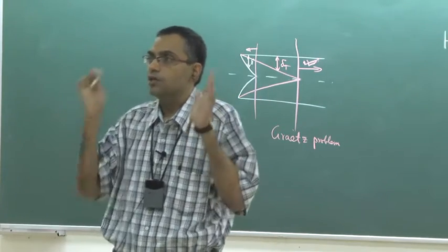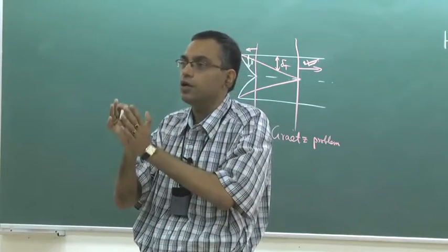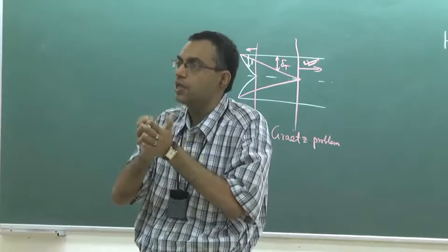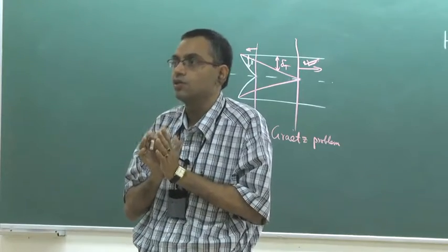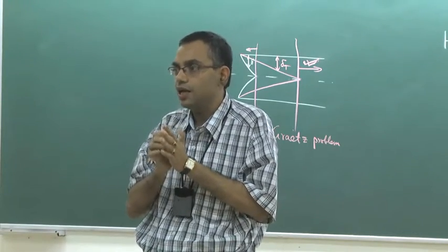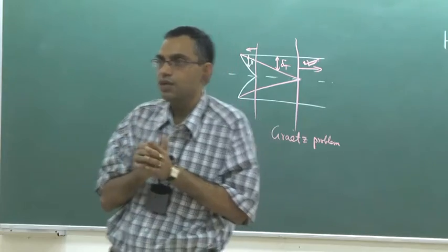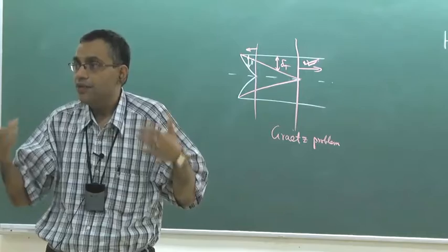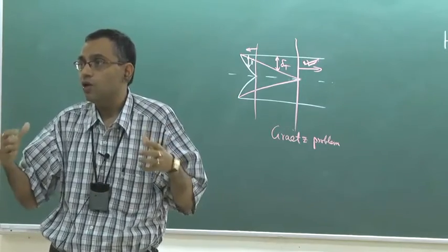But for hydrodynamically and thermally fully developed flow, for internal forced convection, that is a special case where Nusselt number becomes a constant. But in general, the situation changes if the flow becomes turbulent from laminar.